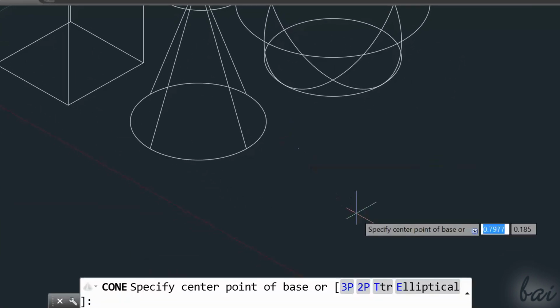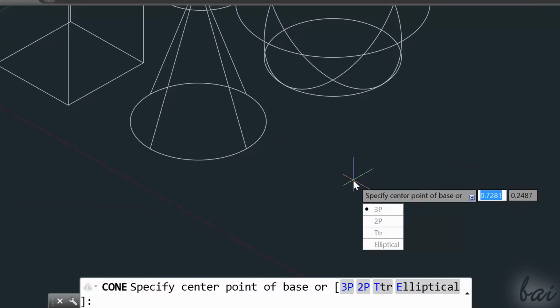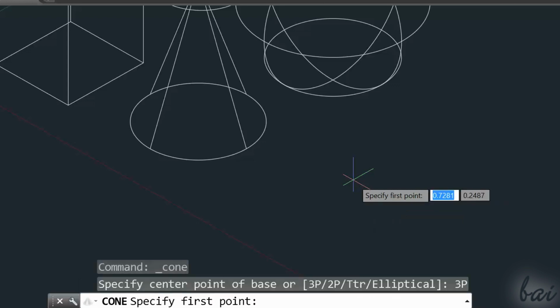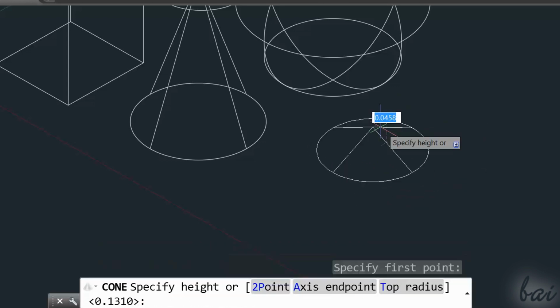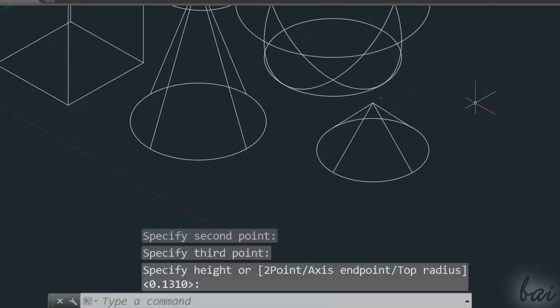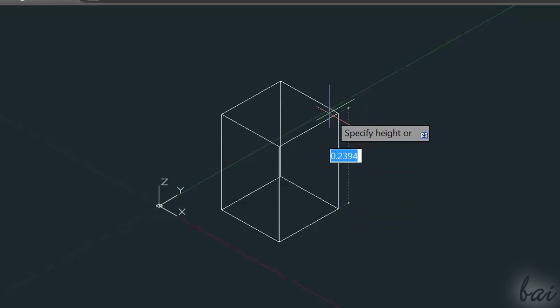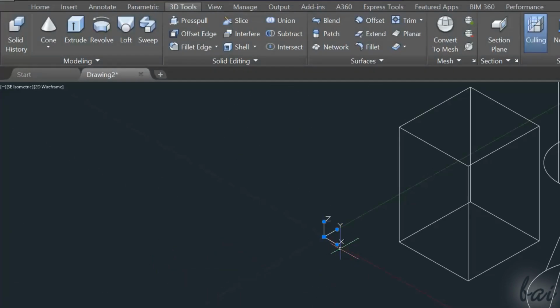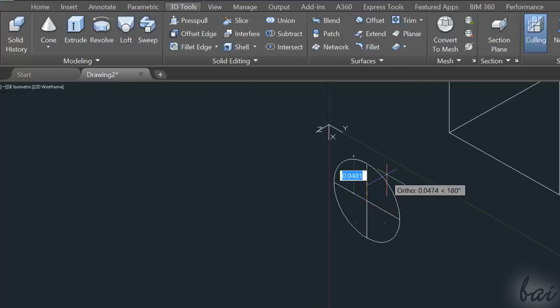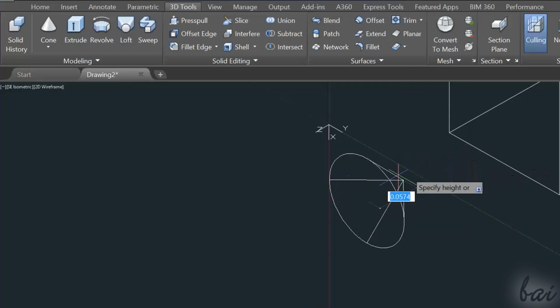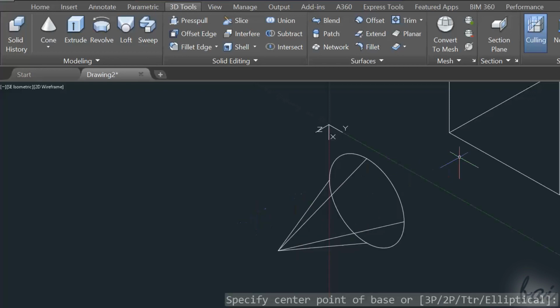As seen for 2D projects, also while drawing 3D objects, you can use the command line below or your down arrow key to choose the way to draw. The base always lays on the ground plane or any plane parallel to it. The height does spread always through the Z-axis instead. If you want to give to the object a different orientation, you need to rotate the Cartesian system using its rounded nodes, as seen before.